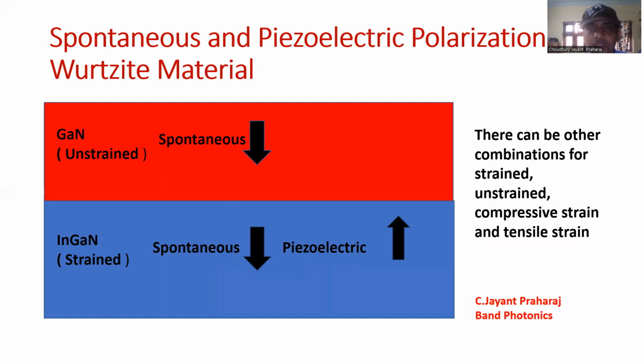When we have quasi-continuous or continuous polarization grading, we get what is called bound charge concentrations. Then the divergence of the polarization basically gives rise to a bound charge distribution, and that enters into the electrostatic and electrodynamic equations of the device, and that leads to different device performance. So those need to be kept in mind and optimized in order to get the best solar cell device performance.